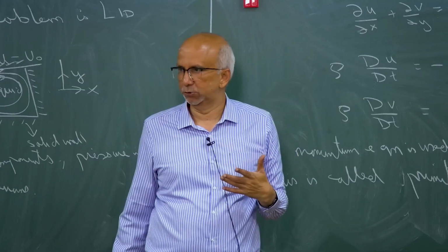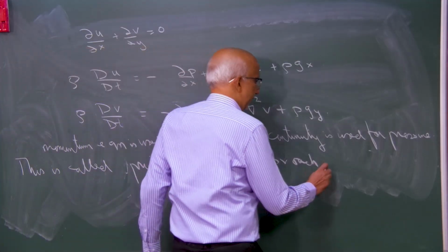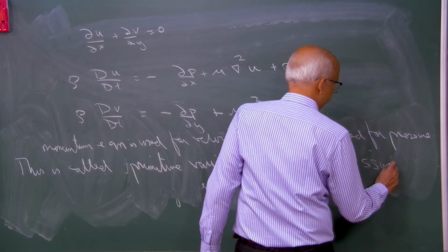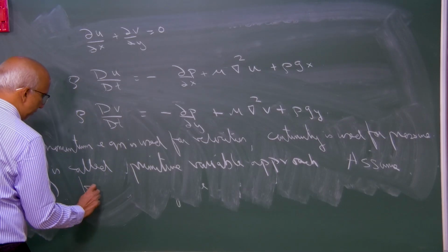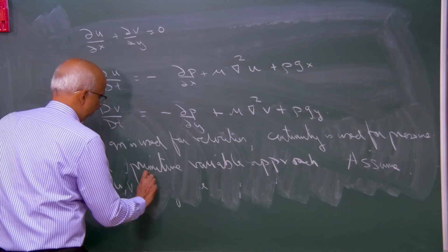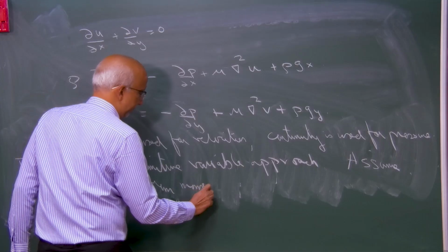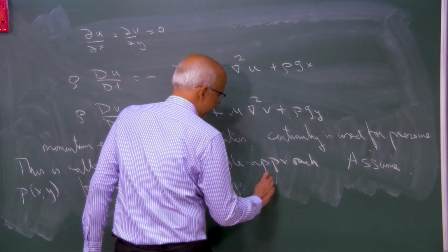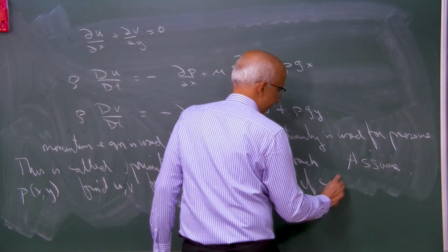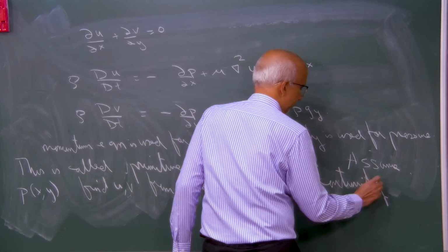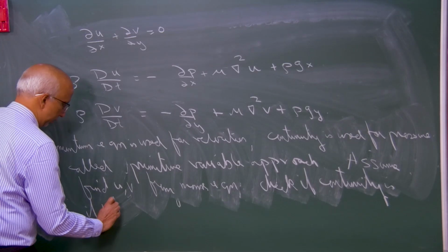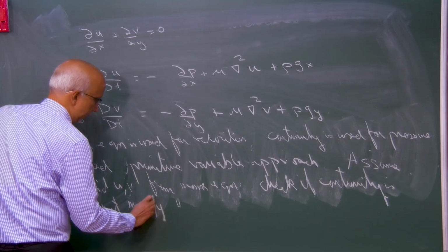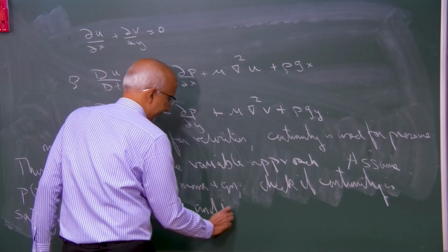So, that is the algorithm which is used, and so the approach is: assume pressure as a function of x and y, find u and v from the momentum equation, check if continuity is satisfied, if not, modify the pressure and iterate.